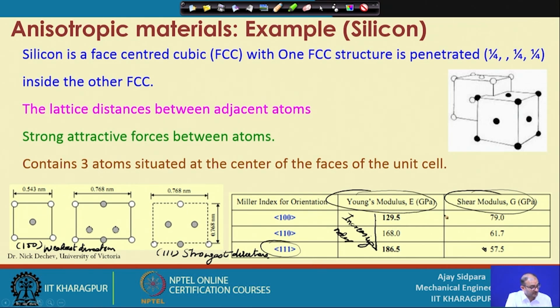Now, consider you are machining silicon in this particular direction, the 100 plane, because the whole structure is coming in its way. So, if your face is this one, your tool will smoothly pass through this particular face. But if you are oriented in such a way that you end up with this particular location, that is the 111 plane, then removal is very difficult in this case.